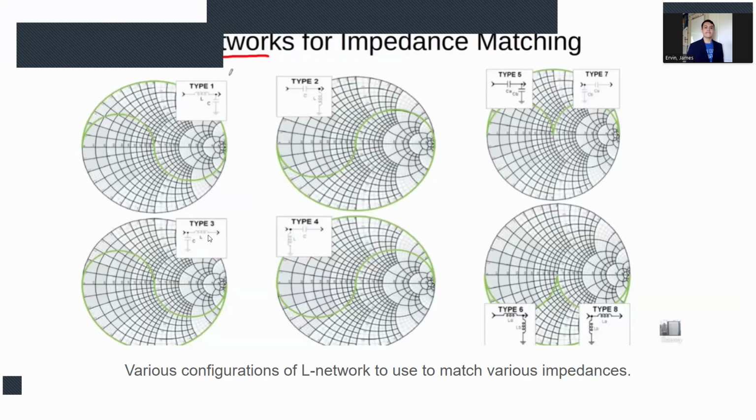So the difference between shunt and series is basically, if you have your center pin of the coax and then the outside of the coax, shunt would just be connecting the center pin to the outside of the coax at that given point, right? And series is just keeping it along with the center pin of the coax.